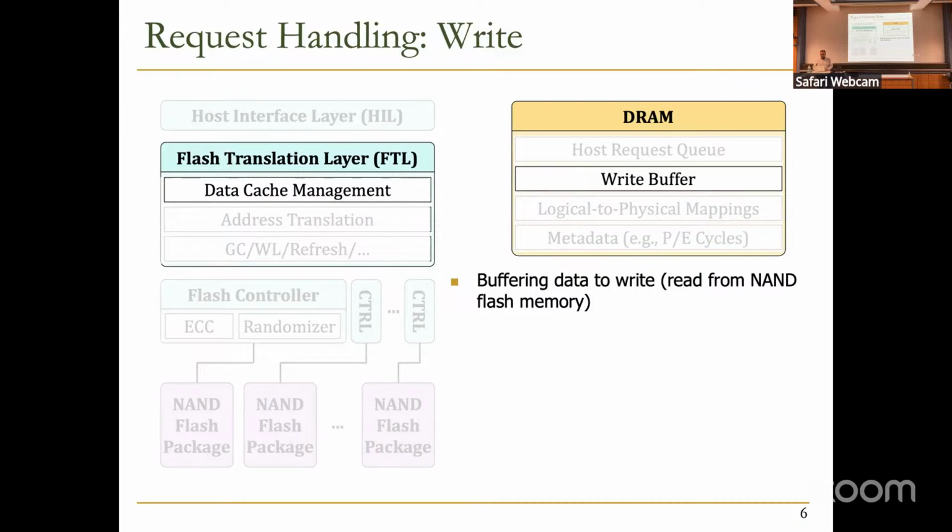However, there is one thing about that DRAM, which SSDs, actually modern SSDs, they provide enough capacitors. So they have some capacitors that provide enough charge when power cutoff happens. So when suddenly the power of the SSD just cuts because of, I don't know, whatever reason, we have enough capacitors that they can provide enough charge to de-stage that buffer to the flash chips.